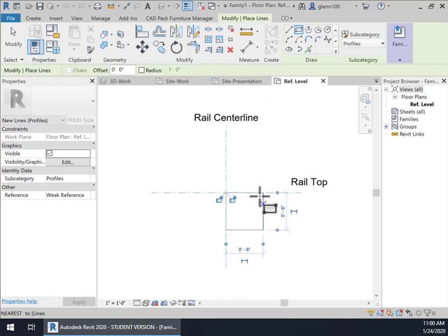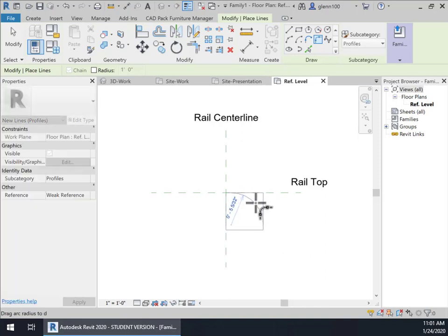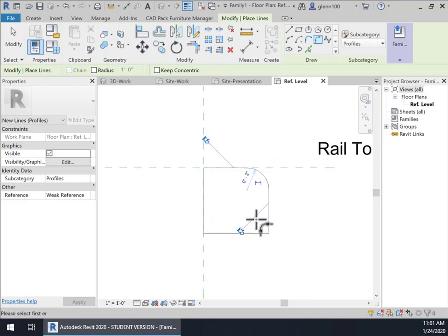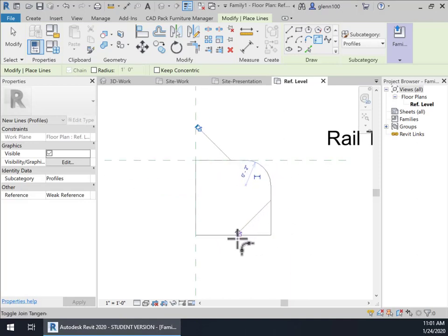And of course, they have a rounded edge in the States. So I'm going to use the fillet command right here. Let's just go ahead and select that, and then we'll pull this back and adjust it in just a second. So there's 2 inches, and that's about right, actually. I kind of guessed pretty much correct there. Okay, so 2 inches. So that's the profile of my curb.